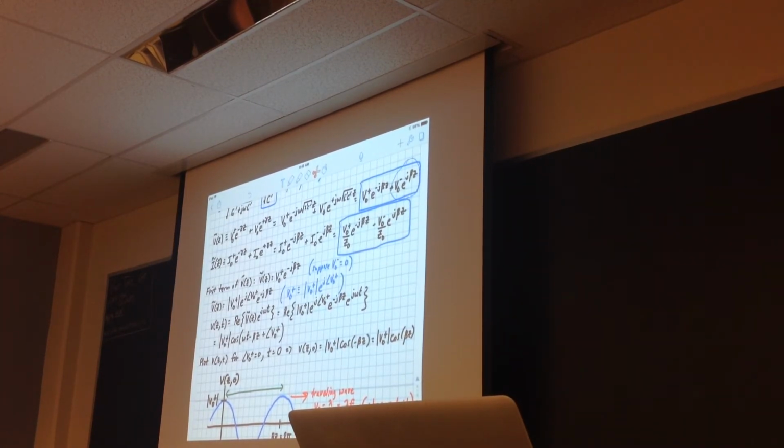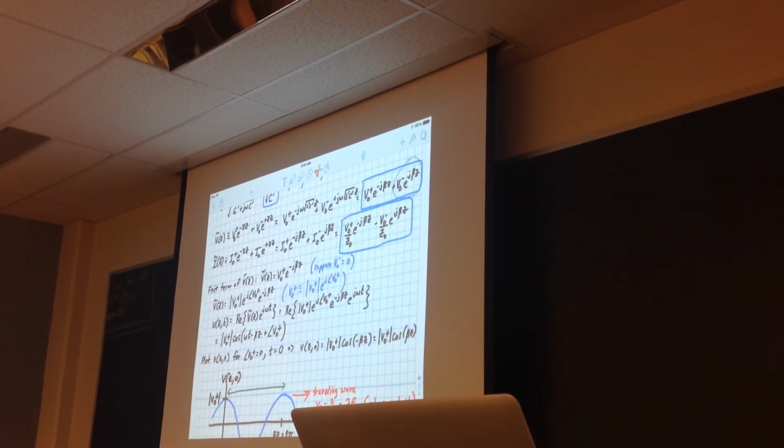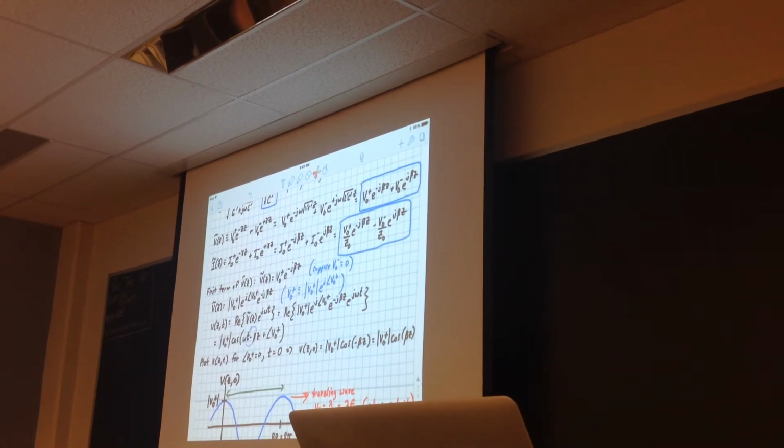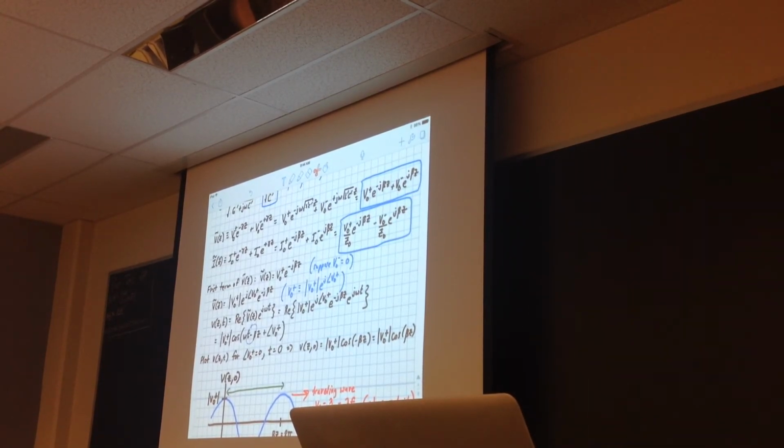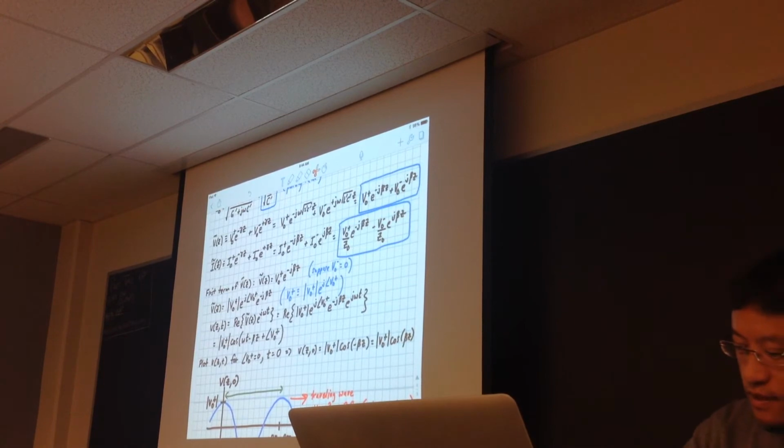Yeah. That other wave is a traveling wave, but it is moving in the opposite direction. Okay? Because you have a sign change. You would have in your voltage time domain equation a plus sign sitting right there. And that means if t is increasing in time as it incessantly does, then z has to decrease for that phase to be the same. So to follow any point on that waveform, you have to decrease z. This whole wave is moving to the left.